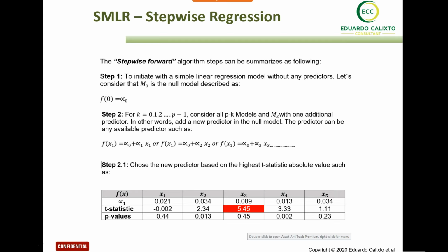In our case, for example, consider a tank. Is it not better to get only the thickness of the corrosion or pitting, rather than also getting the temperature inside the tank or the pH inside the tank, to predict our remaining useful life? So that is the question. In the stepwise regression method, what this method does is define which of these independent variables or predictors are more important to use in our prediction.